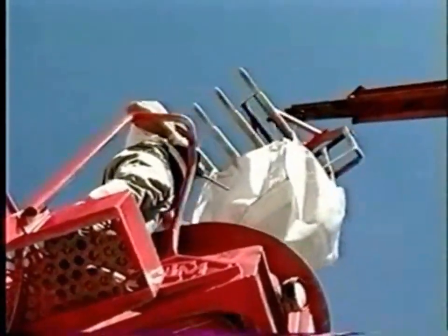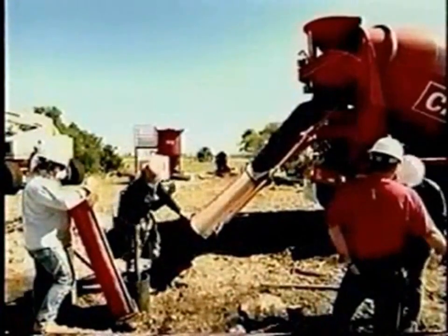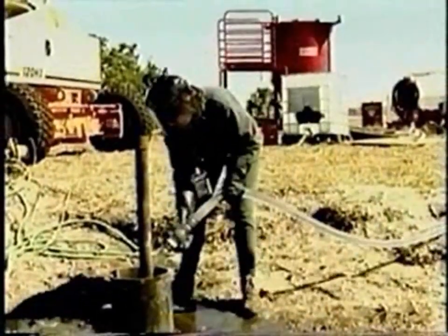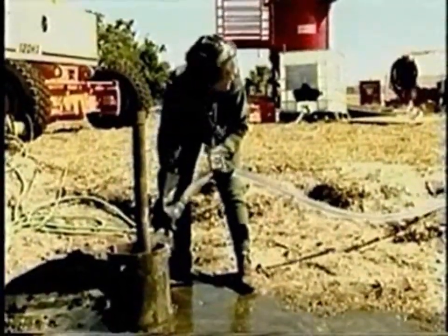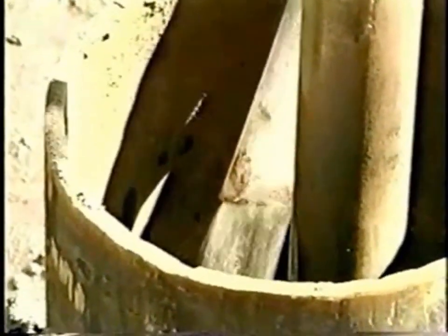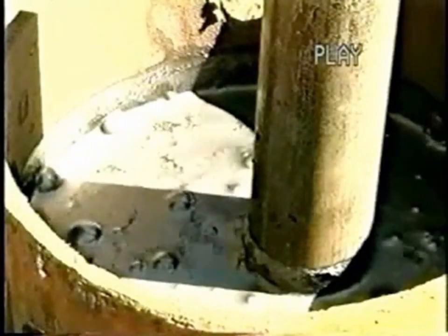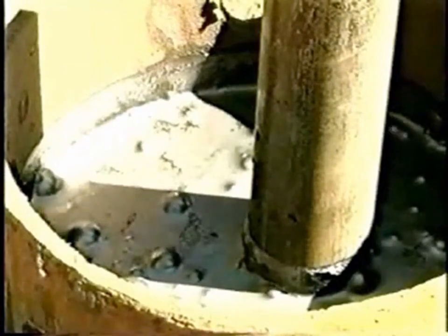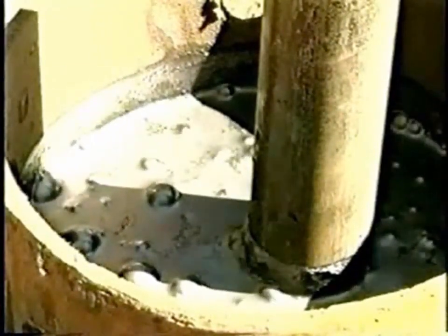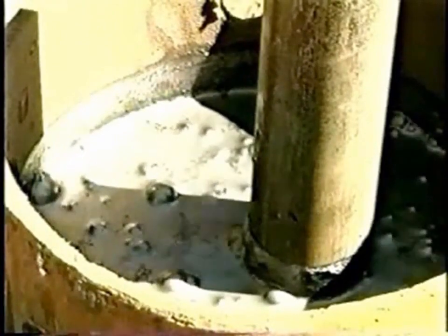The gravel-iron mix can arrive on site pre-measured and ready for placement in the casing. When filled to a level 1 foot above the groundwater table, a sulfuric acid rinse is introduced inside with the bottom plug still intact, so that the solution remains inside the casing for 12 hours. When the acid rinse is introduced, it has a pH of approximately 2. Once in contact with the oxidized iron filings, the pH shifts to 5.